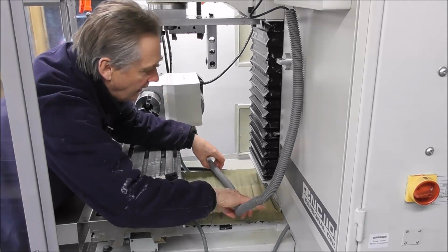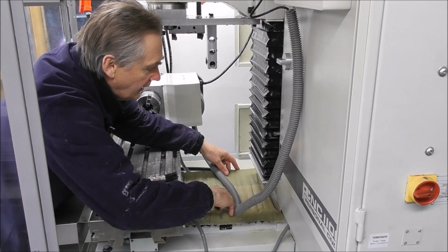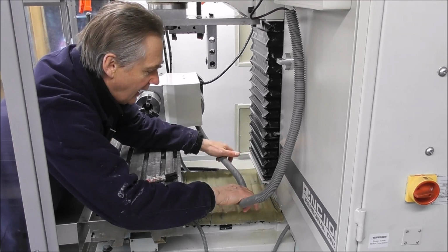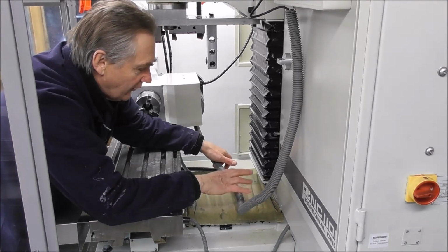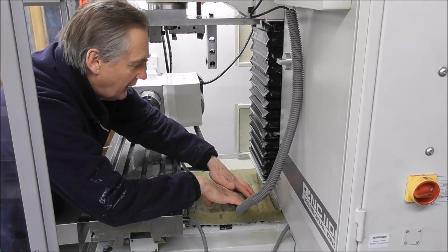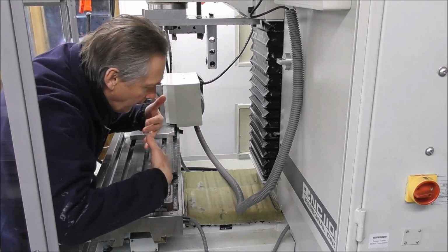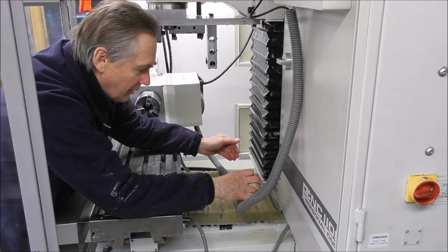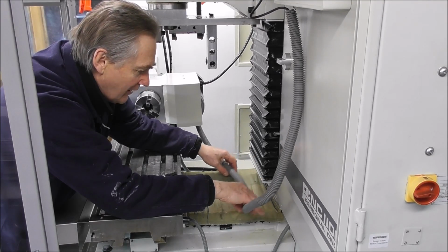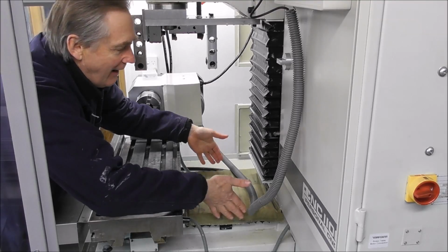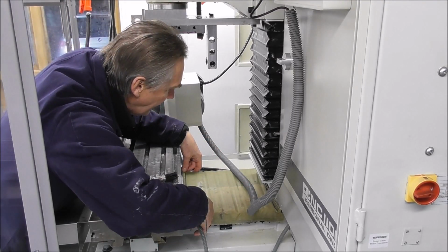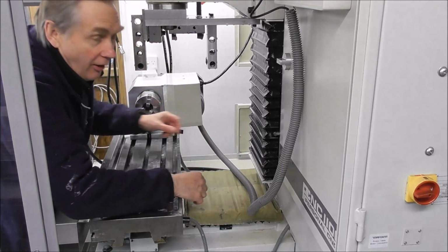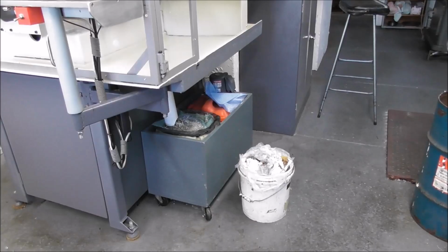That holds the cotton cover taut and helps to filter and deflect a lot of the abrasive particles and swarf, and also stops it from getting in between the bellows, so that when the Y-axis goes back that way, it's less likely to crunch up and split the bellows and cause problems. So there are several benefits to having a top layer on there and holding it down with a couple of wires or small diameter rods. Alright.